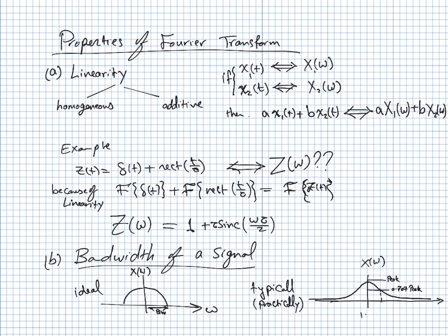This is the half power bandwidth, and the half power bandwidth is going to be this width. So you pick the point where the peak value is reduced to 1 over root 2. This is the peak multiplied by 0.707, which is basically 1 over root 2. It's going to be some value here.